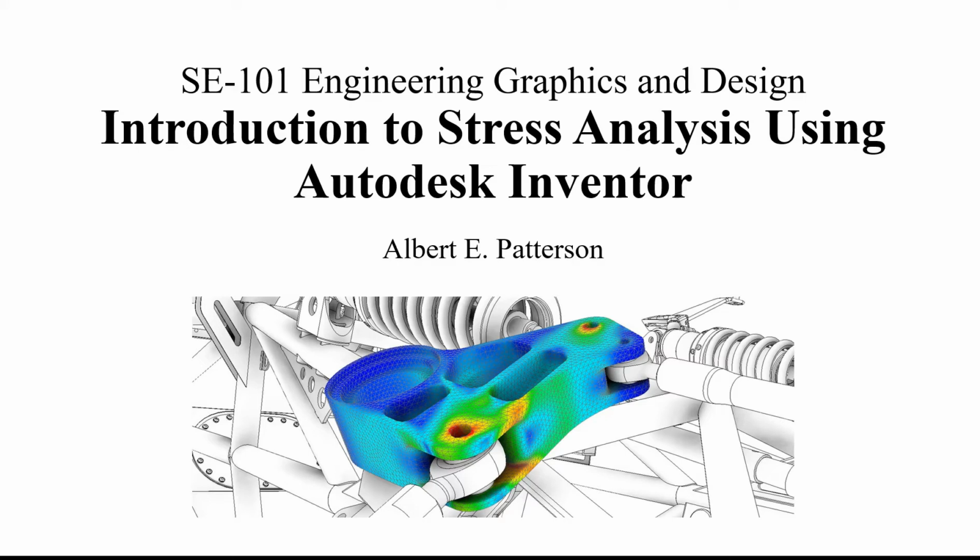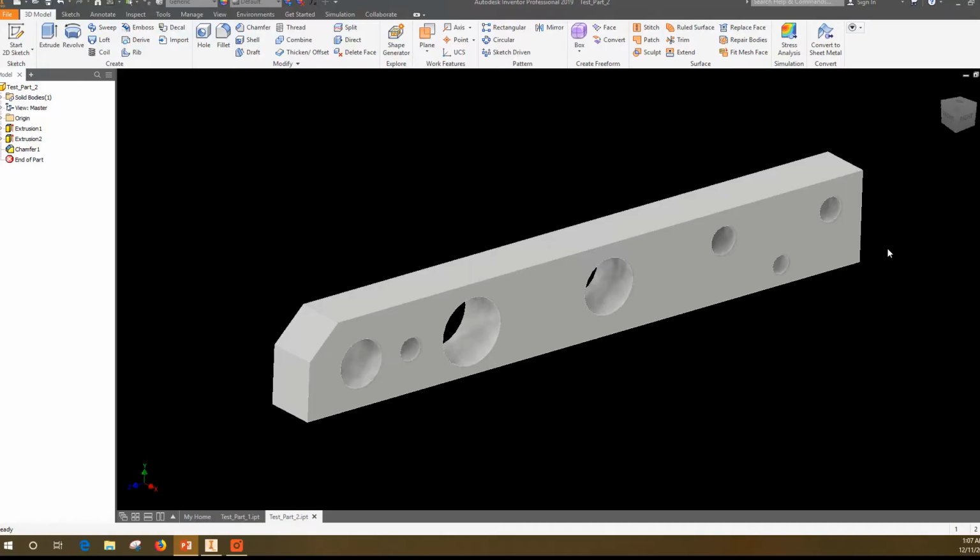So today we're going to do a really quick case study using a very simple part. Remember, in the first part, there are two ways we can apply a force to our material. The first one is applying a standard force at a point. The second is applying a pressure, which is a force distributed over an area. The first case study that we're going to do in Inventor is this geometry. It's just a basic beam with a chamfer on the end, fixed at one end, with a bunch of randomly placed, randomly sized holes. We're going to apply a force to this one and look at how the material reacts.